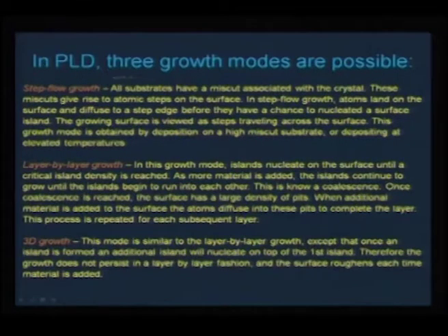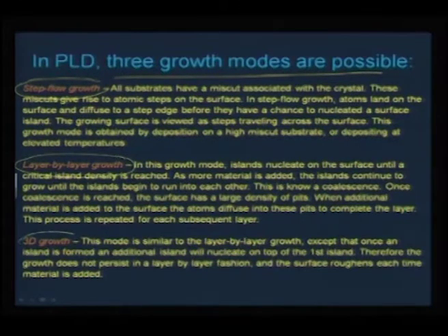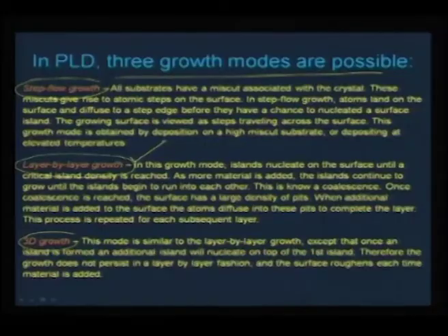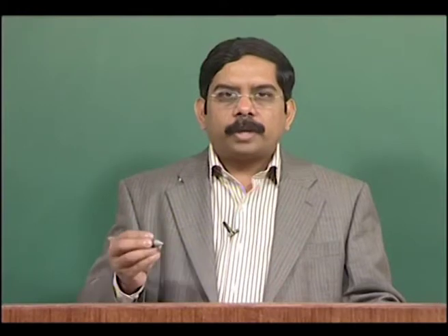In PLD, just like the way I emphasized in the earlier lecture on MBE, the growth mode also proceeds similar to molecular beam epitaxy, in that it can be a step flow method, a layer by layer growth, or three-dimensional growth. As I told you, pulsed laser deposition, because of the high kinetic energy involved in this plume dynamics, usually gives layer by layer growth, which is the most favored growth mode. But 3D growth mode brings about a lot of roughness in the film, and therefore that is not desired. So we need to have an idea about how to get layer by layer growth.